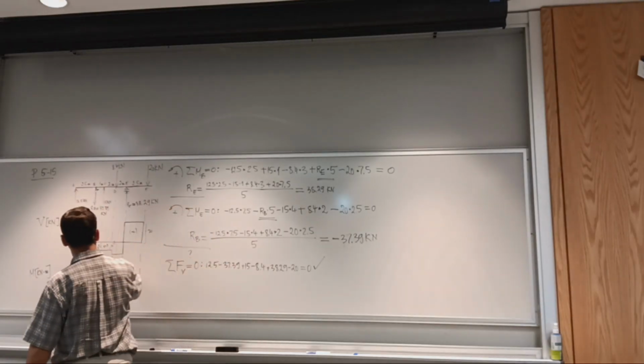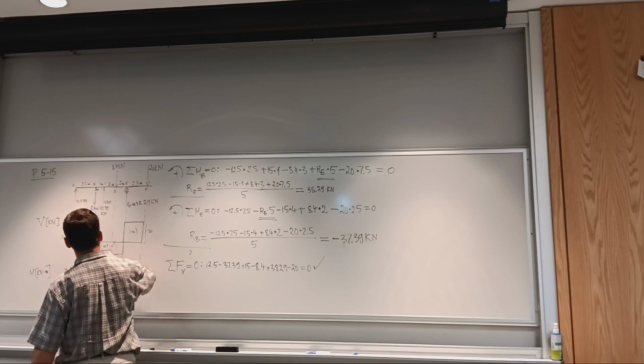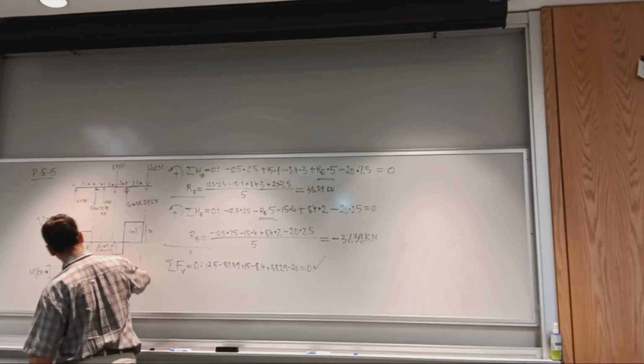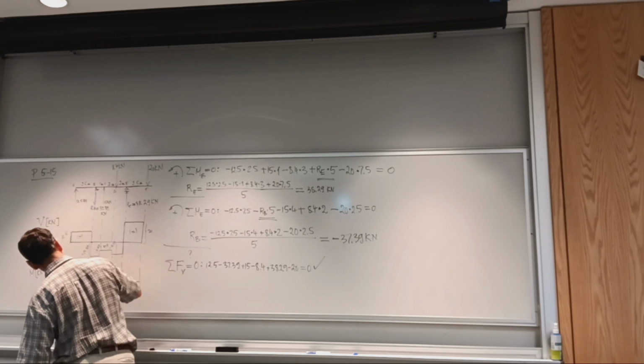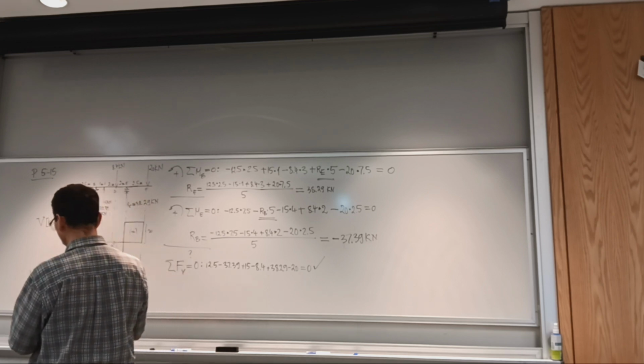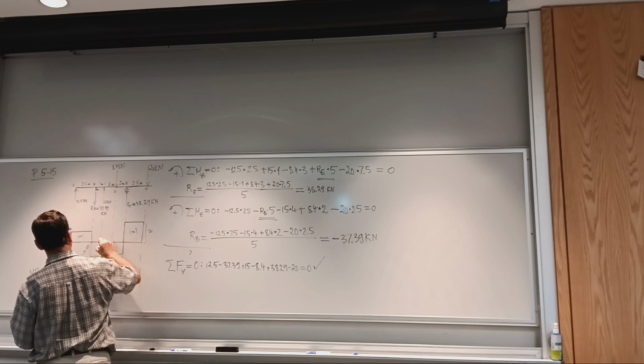Okay, let's move forward. So we have the slope changed to a lesser slope, and it remains linear up to point D. Let's calculate the moment at point D so that we know how to continue the diagram. So I have 6.36 positive, and I'm going to add to it the area, this area here.